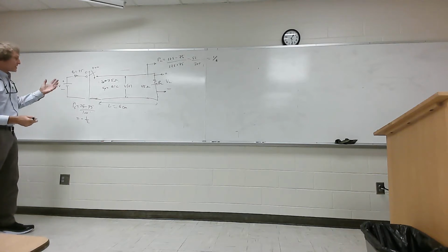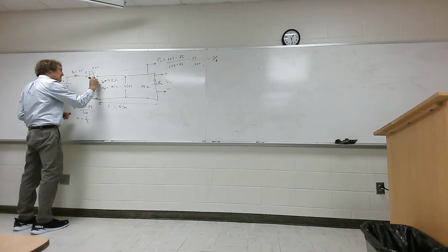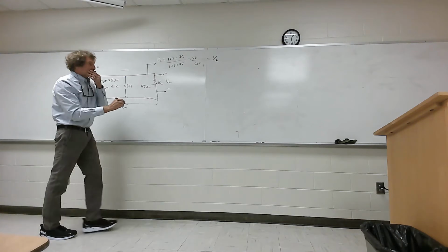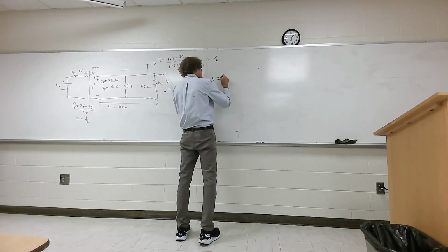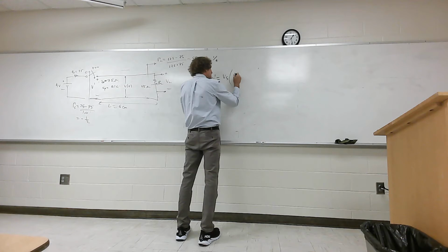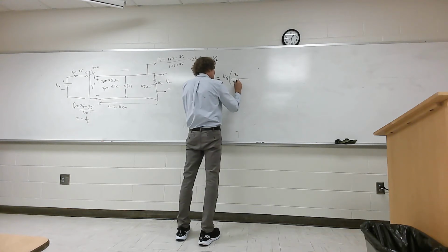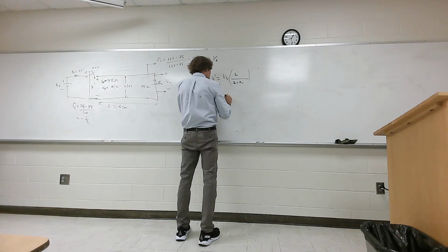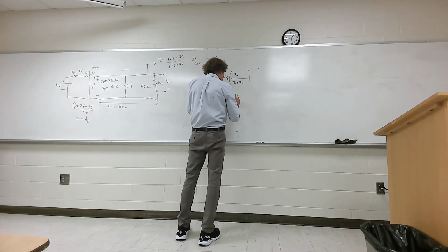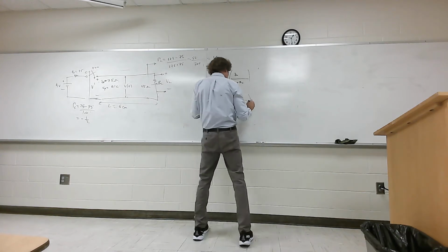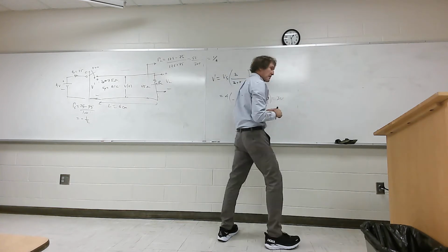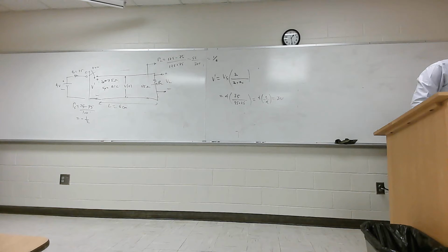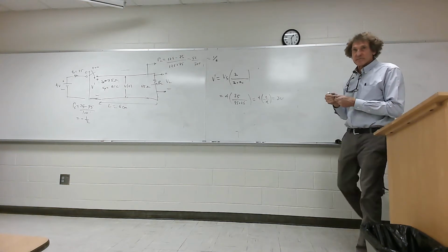All right. Then when we get our V prime, which is this voltage that goes on the line right there, what is that going to be? Well, the source voltage is 4 volts times Z naught over Z naught plus R source. So this is equal to 4 times 75 over 75 plus 25. Well, that's 4 times 3/4, 3 volts. Y'all agree with that? I don't mean to bore you with this one, but I have to make sure everybody sees this at least once. So just bear with me.